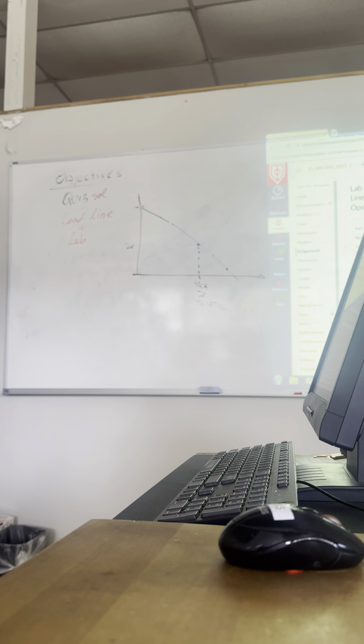What if you added more power supply? Well, then you're moving it from under. You with me so far? Yep. Can we only change RC or can we change VCC as well? Again, in a circuit you can do pretty much what you want. Right now I need you to keep VCC and RC the same, to just get the load line based on a bunch of changes to RB, basically a bunch of changes to IB.